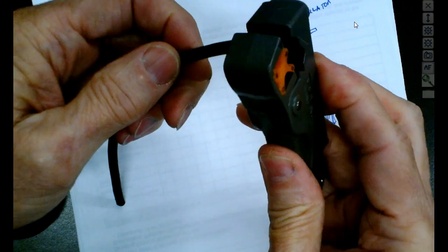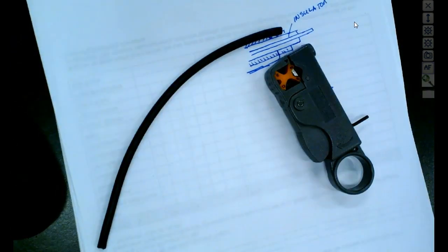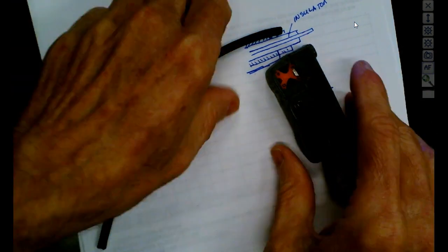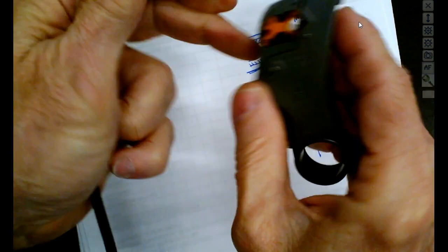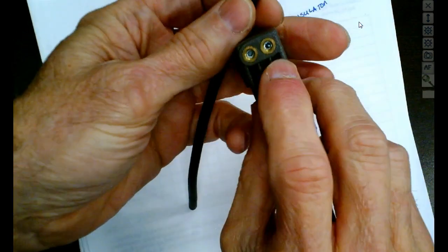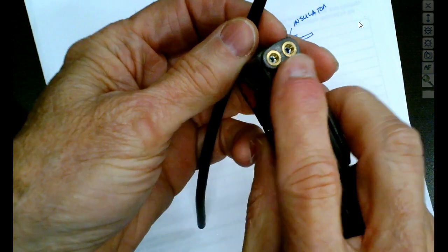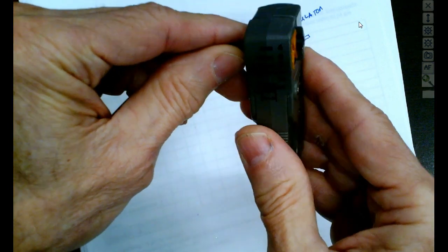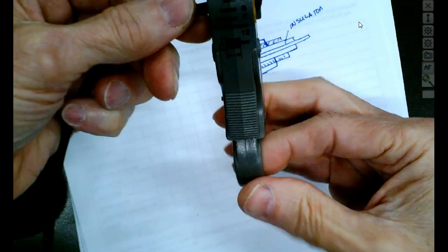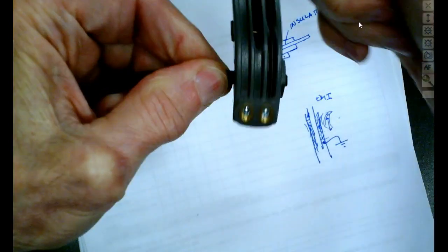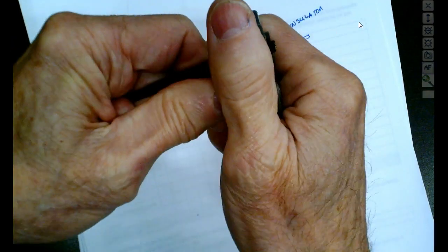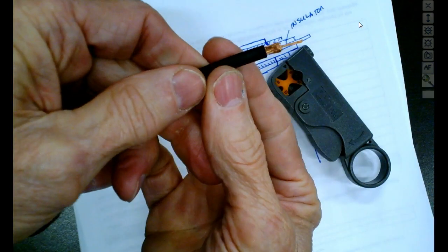So what we'll do is we'll lay this on the tip. And we've already adjusted this. So you scrap some cable while you're setting the thing up. So here's Allen wrenches right here that controls the two blades. Now once you get it set right, then this guy is not going to touch the conductor, and it's not going to touch the shield. So we just put it on there, we grab our finger, and then we just spin it around. And then when we feel it spin freely, we come over here and grab it real good, and we pull it off. And this is the way the strip cable looks.